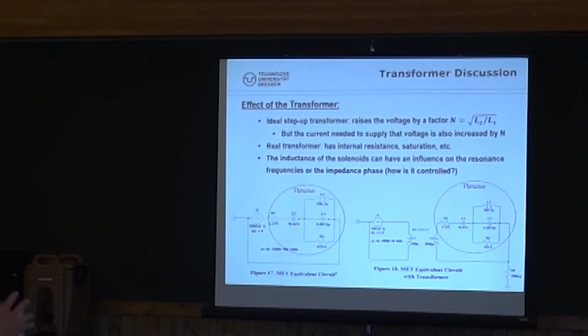Yes. Every transformer has leakage inductance based entirely on the geometry of the windings. So that will create a series-tuned circuit with the capacitance of the actuator, which will greatly affect the response at a frequency to which it's sensitive. Well, we did the experiment with a flyback transformer here. 6 to 1. Very high leakage inductance. Very high leakage inductance. Yes, okay.